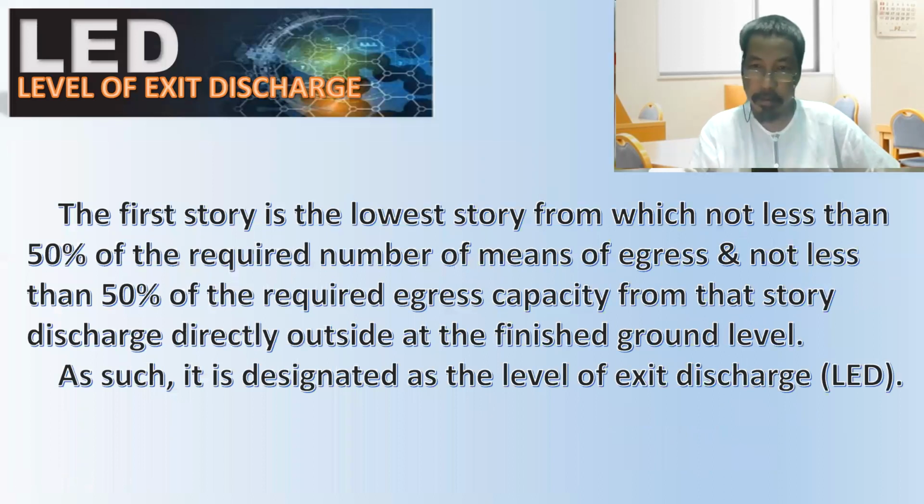Therefore, in that case, the first floor is the lowest floor from which not less than 50% of the required number of means of egress, and not less than, take note, it is easier to understand: 50% or more of the required egress capacity from the story discharge directly outside to the finished ground level.